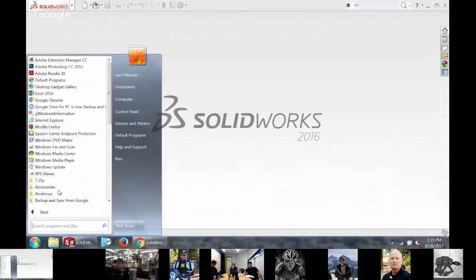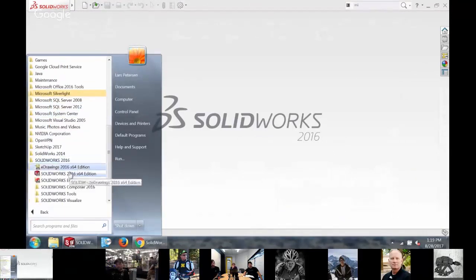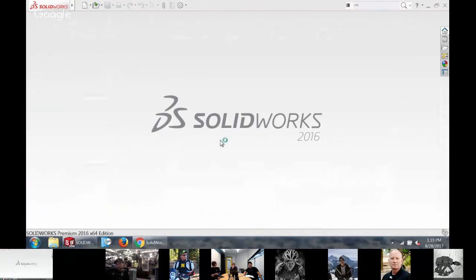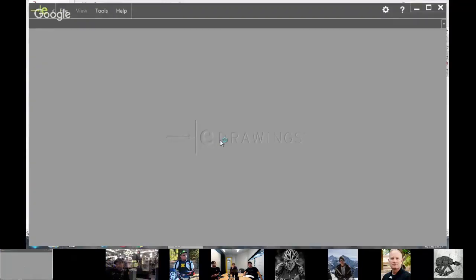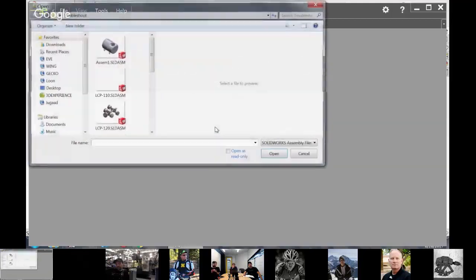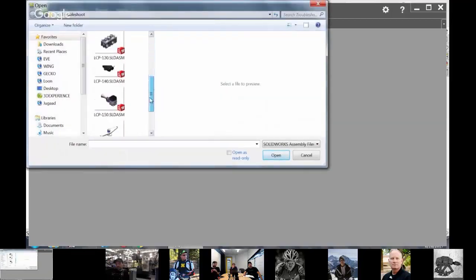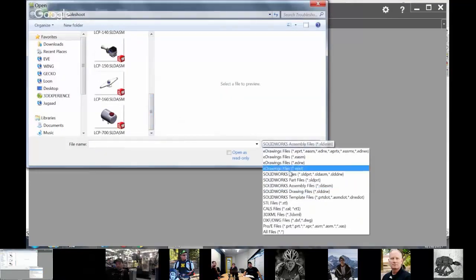Okay, there's some other tricks that I can use. One of them is using SolidWorks eDrawings as a viewer. As long as I didn't save the assembly with all those issues, the issues that I'm getting actually were done at the sub-assembly level. So at the top level assembly, last time it was saved, it was fine. If that's the case, and I go into eDrawings and open it up, eDrawings is a free program with SolidWorks.